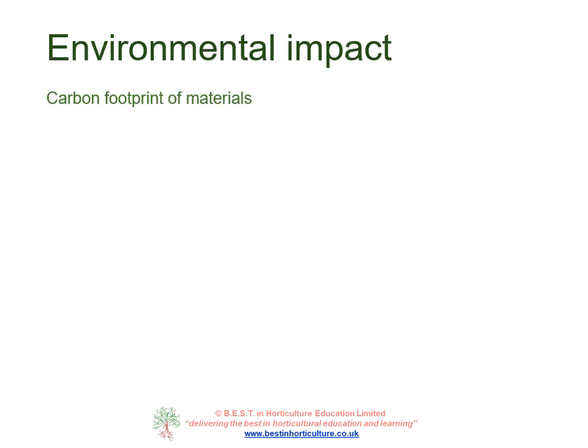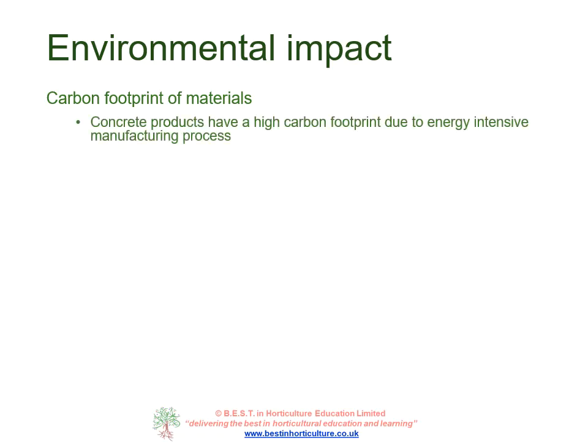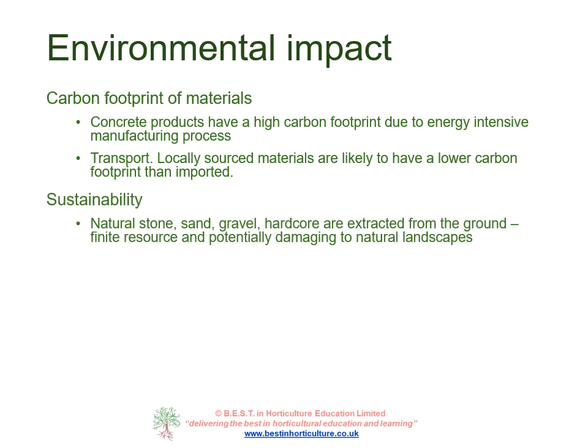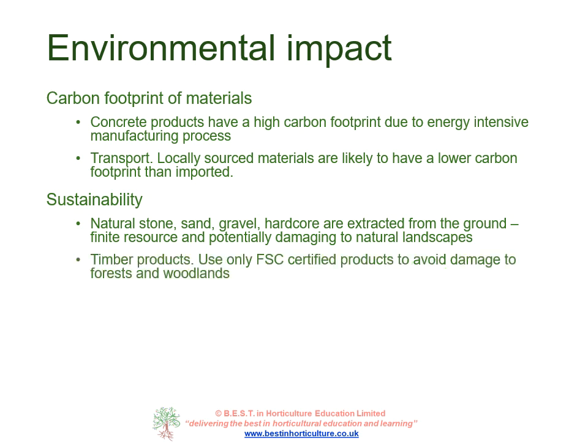Environmental impact is particularly important these days, so we need to consider here the carbon footprint of materials. Concrete products have a very high carbon footprint due to the energy-intensive manufacturing process. Transport: locally sourced materials are likely to have a lower carbon footprint than those imported from overseas. Sustainability. Natural stone, sand, gravel, hardcore are extracted from the ground. This makes them a finite resource and potentially damaging to natural landscapes in their extraction. Are there any alternatives? Timber products: use only FSC, Forestry Stewardship Council certified products to avoid damage to forests and woodlands.